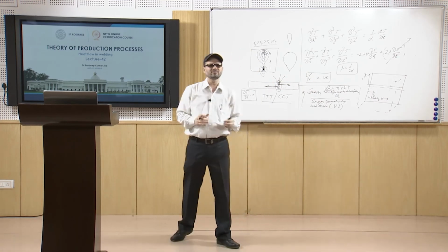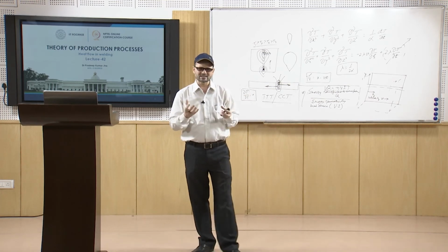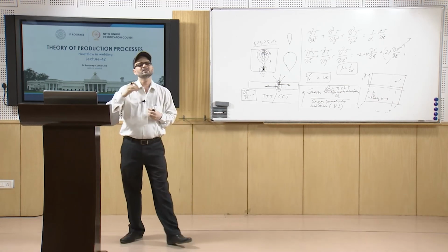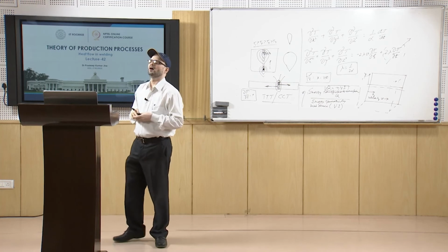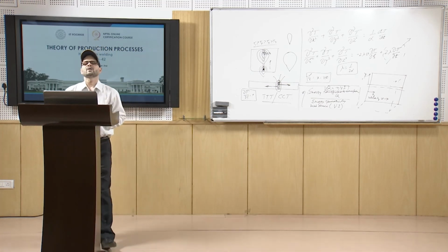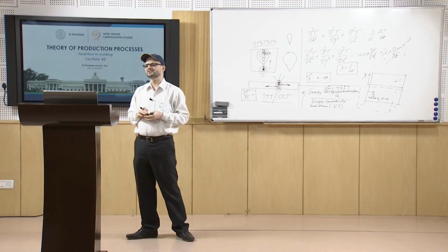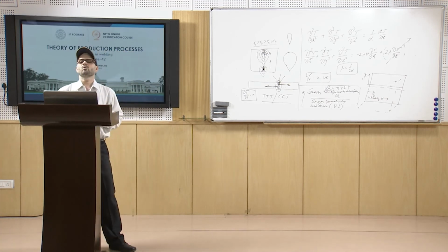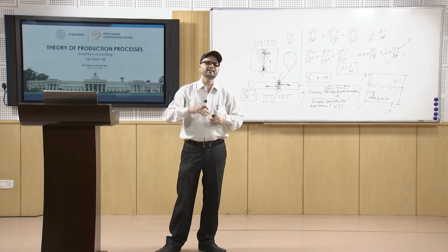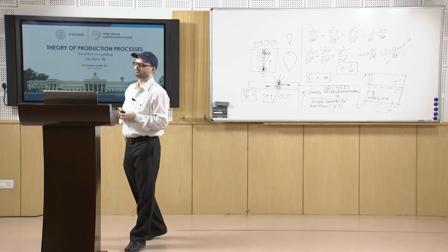So, the dissipation of heat from the arc to the surroundings is lesser, and the arc efficiency or thermal efficiency of this process is better as compared to other processes. Electroslag welding is better than many but not as good as SAW because of the water cooled copper shoes used in these cases. That has some adverse effect on the thermal efficiency of the process.